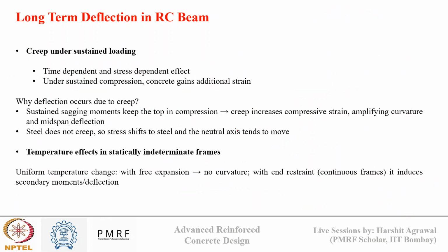After shrinkage, another factor which contributes to long-term deflection is creep under sustained loading. So, quickly reviewing what creep is: creep is a time-dependent and stress-dependent effect. Shrinkage was a time-dependent and load-independent effect. Here we have a time-dependent and stress, or we can say load-dependent, effect. It results from sustained compression of a reinforced concrete section under loading, which results in additional strain generation in concrete, which results in deflection.